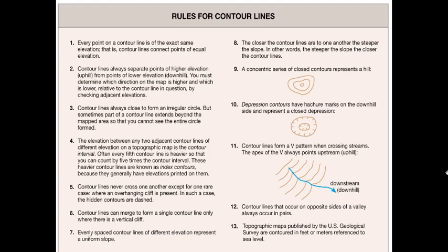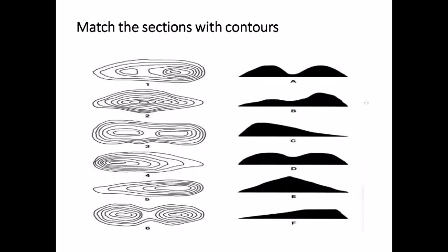When you have a contour map, you should refer to the index contours, and they would tell you if at the center the elevation is more or along the other side elevation is more, because up till now we've talked about contours by saying that the center is usually the location where the elevation is the highest.